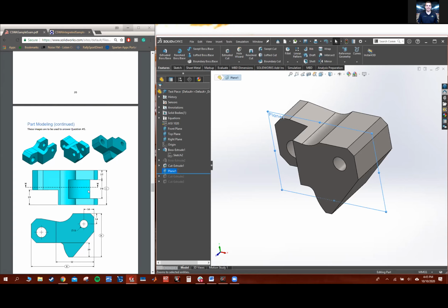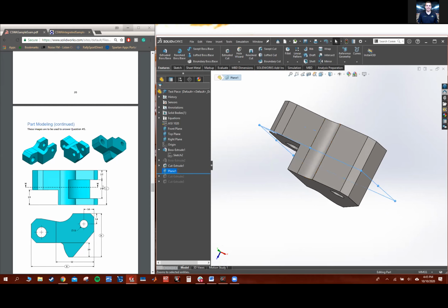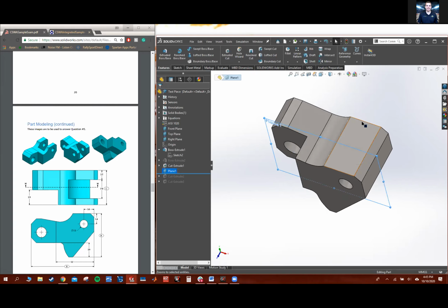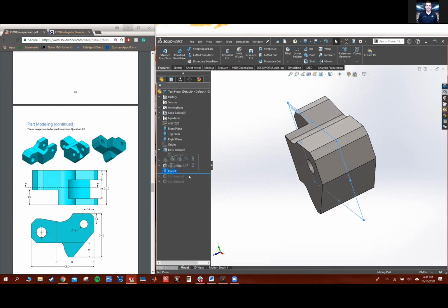So I put this plane in here by doing subtraction of this length plus this mid length. So it's 12 plus 12. So this plane is 24 millimeters from this side over here. And that's the middle of this piece. So I added this plane in, so now I have a sketch plane.